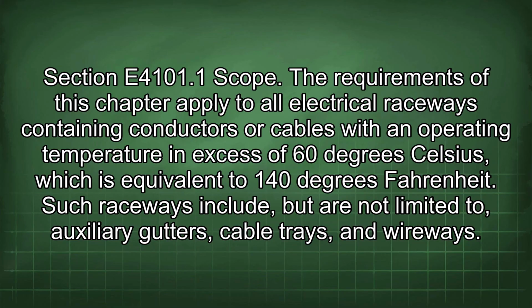E4101.1 Scope. The requirements of this chapter apply to all electrical raceways containing conductors or cables with an operating temperature in excess of 60 degrees Celsius, which is equivalent to 140 degrees Fahrenheit. Such raceways include, but are not limited to, auxiliary gutters, cable trays, and wireways.